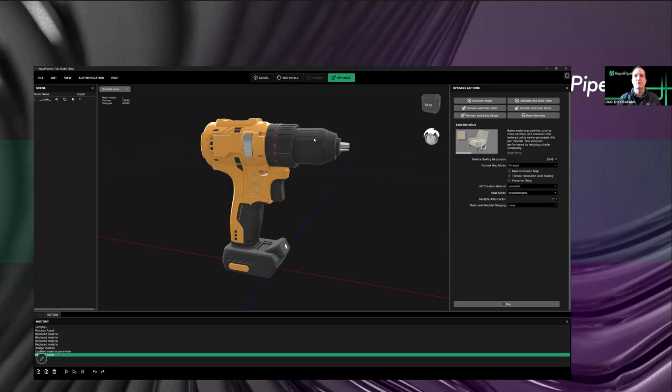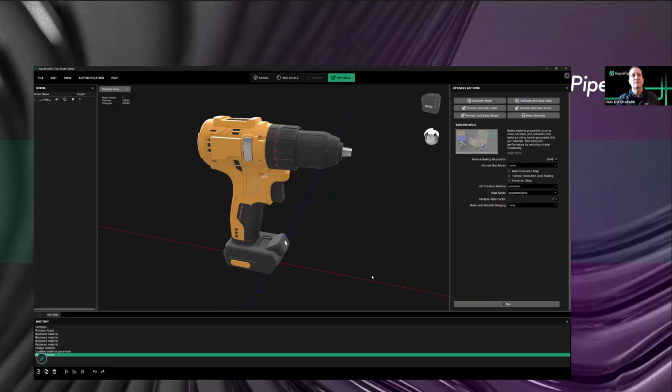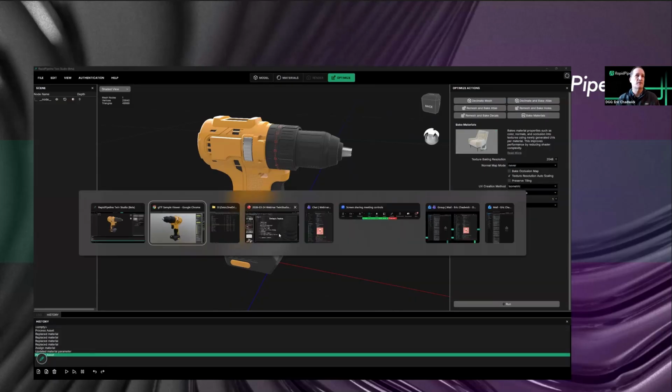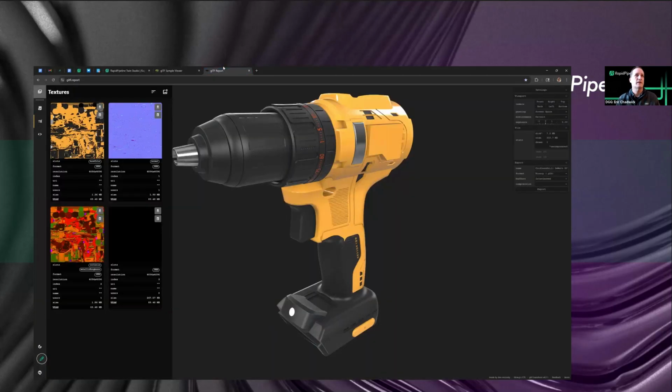So if I have a tiled normal map across one of these, it'll then bake that for that material, but not anything else. And then you can say also, hey, I don't want to bake any normal maps. Even though I'm decimating down to a lower res, I don't really care. Just show me the shading that I get from that and don't bake a normal map. So that's that option. And we looked at it here.